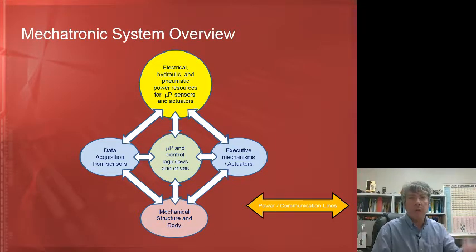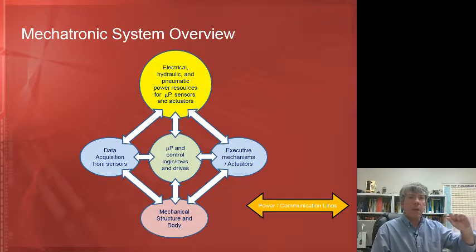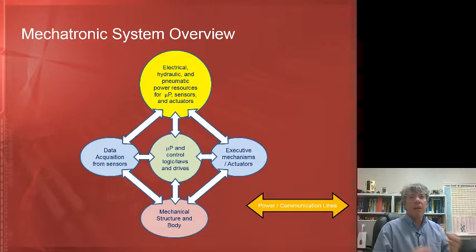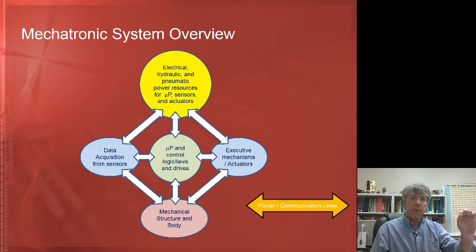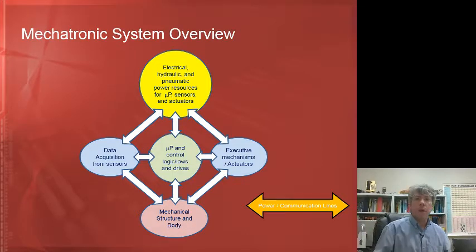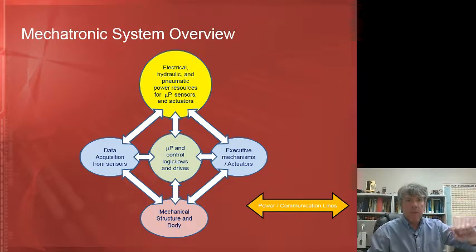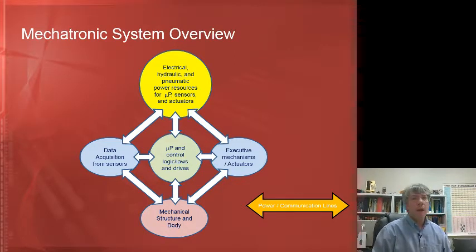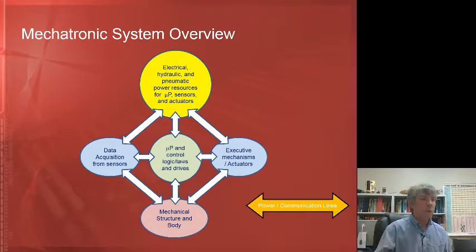This is similar to what you do when you walk in a room and you turn on the light switch. The action of turning the light switch on doesn't require a lot of work. It's not that action that generates power to light up the lights. All you're doing is using a small mechanical signal to control a larger electrical signal. There's a lot more power going to the lights than the force times distance that it took for you to flip the switch. So the microprocessor flips the switch, but what that does is that directs the drive to redirect power to the motors in the way that's required.